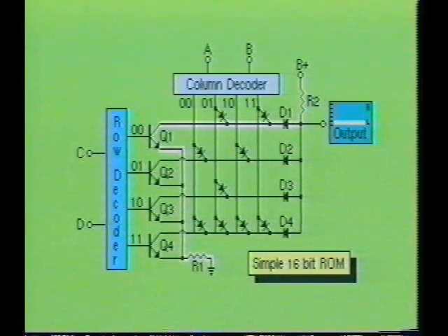The value of resistor R2 will be much greater than resistor R1, therefore the majority of the voltage drop will be placed across resistor R2. This places the bottom of R2 close to ground potential, therefore a low is being produced at the output.